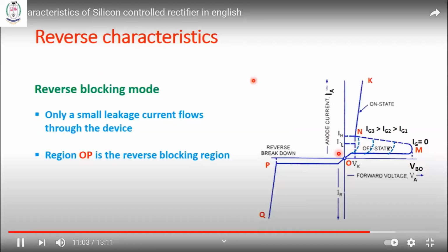So from that, what you have to understand is a small leakage current is flowing through this junction. I keep on applying the voltage. You just understand this is the VI characteristics. In this VI characteristics, you see a small leakage current is flowing. I keep on applying the voltage, and once it reaches its breakdown voltage, what happens?